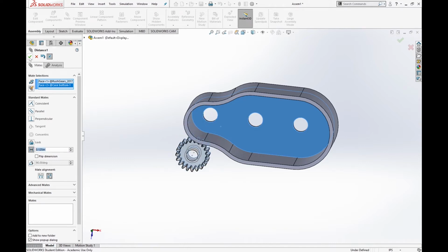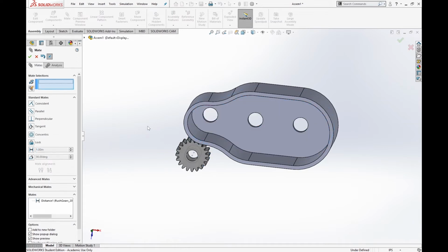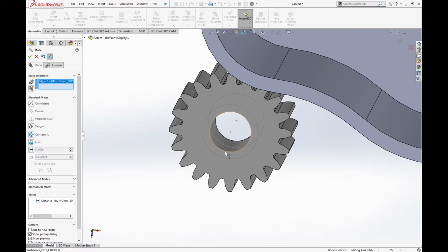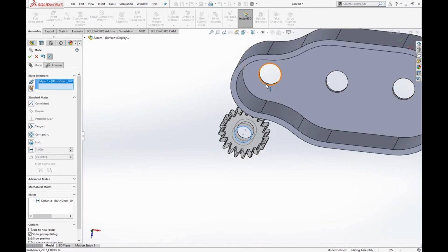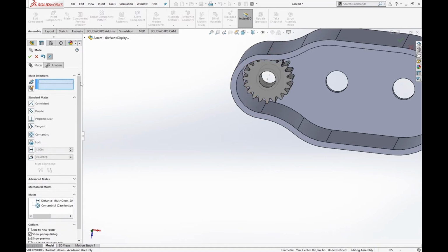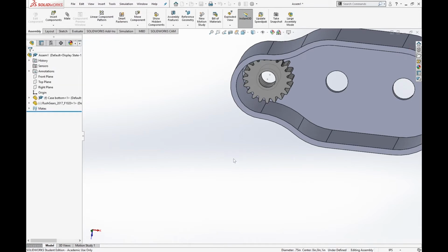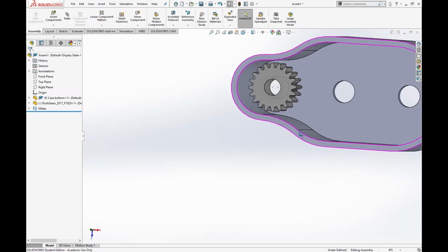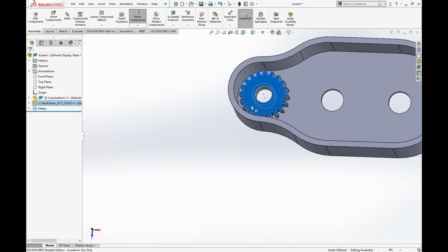You do what you guys do. We do an 1/8 inch. It's worked for us. And then what I'm going to do is that this shaft hole, I'm also going to make it centered to that hole there. So then that is the placement of my first gear. So this gear is not fully constrained. As you can see under here, it's still underdefined.